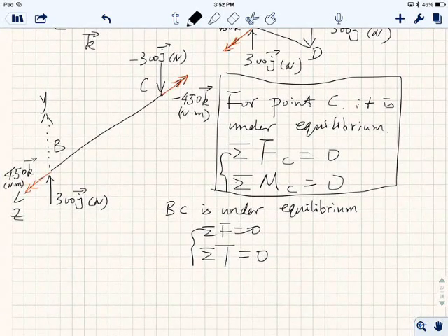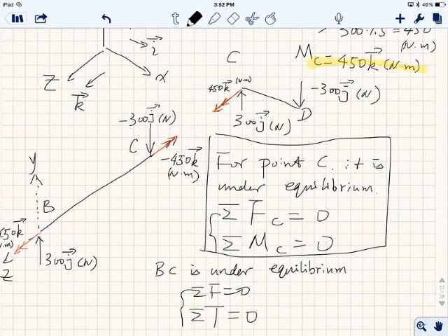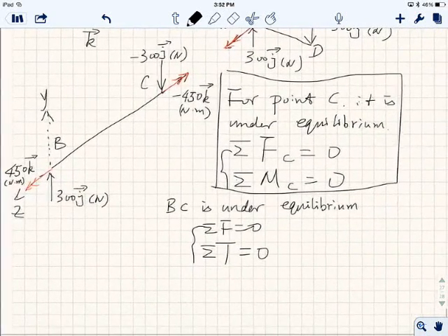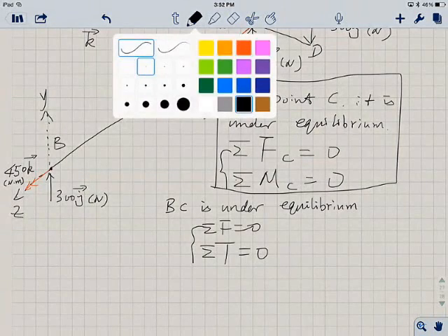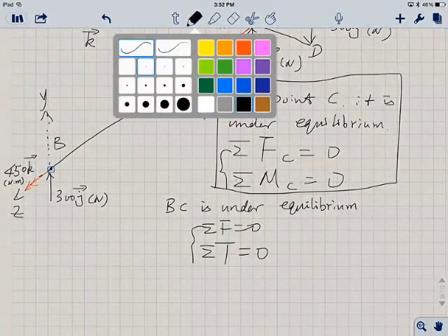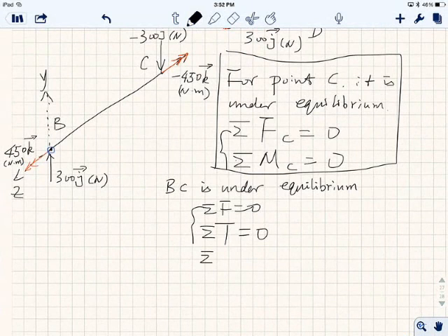So, why is that? So, see here. When we treat CD, CD is a cantilever beam, right? But at the same time, BC is also a cantilever beam, right? Because B is totally fixed, connected to the A, but C this time is free. So, we have a cantilever beam over here. So, imagine this point, this blue point over here, is your fixed point. This force over here is also going to cause some bending, right? So we also have summation M equal to 0 in this case for BC.